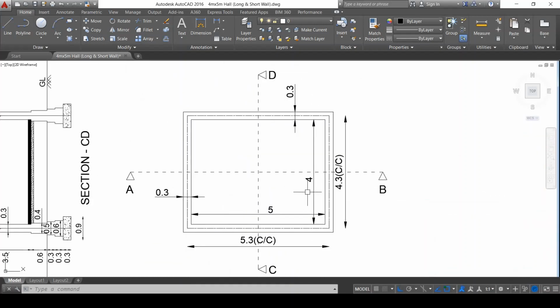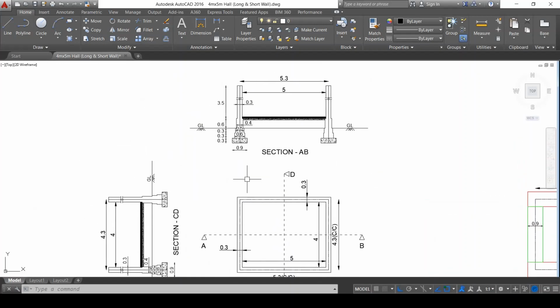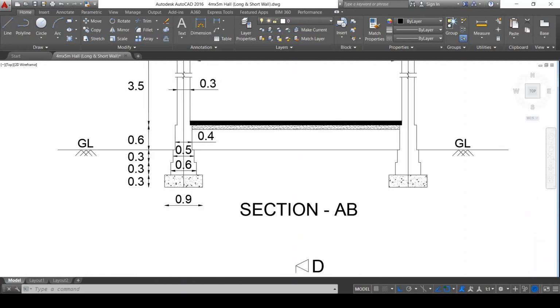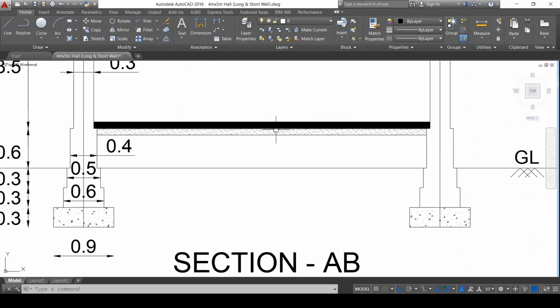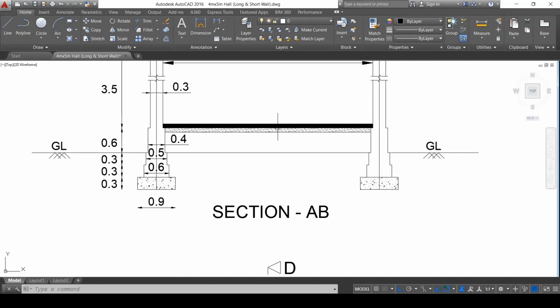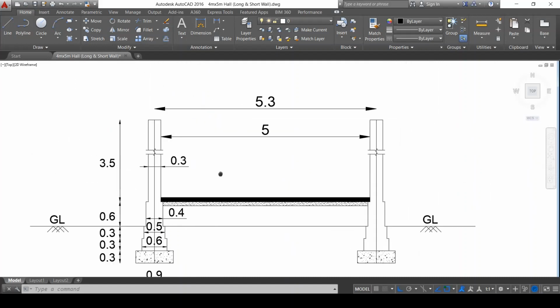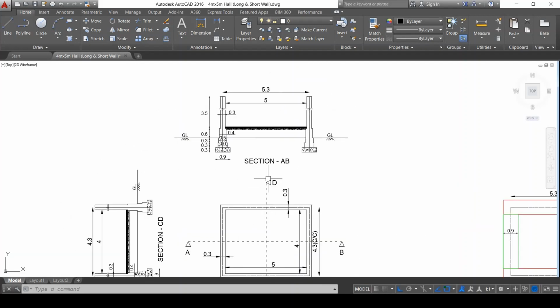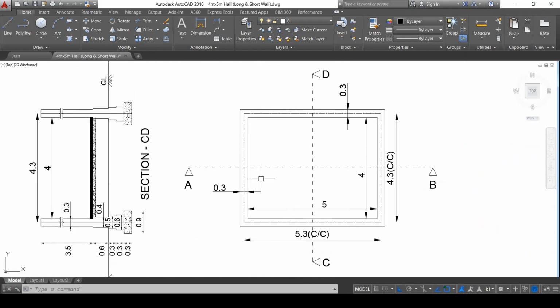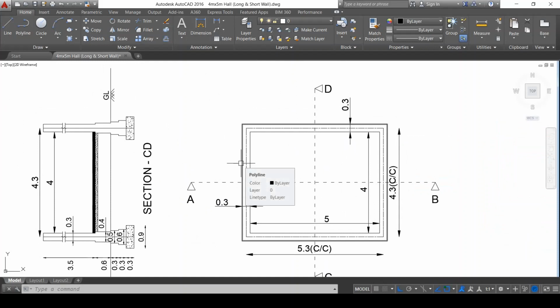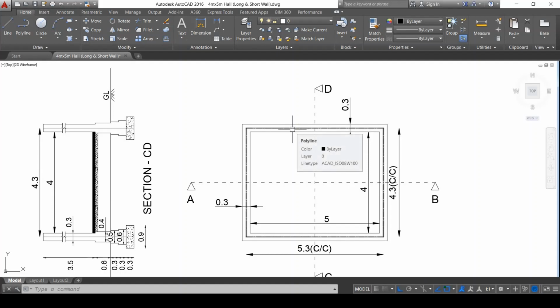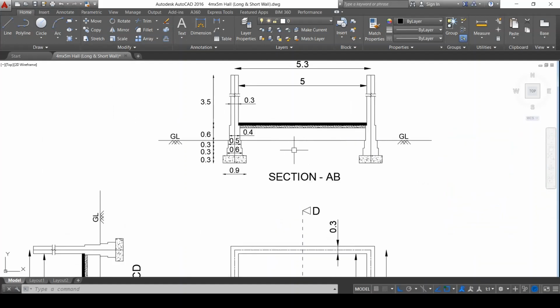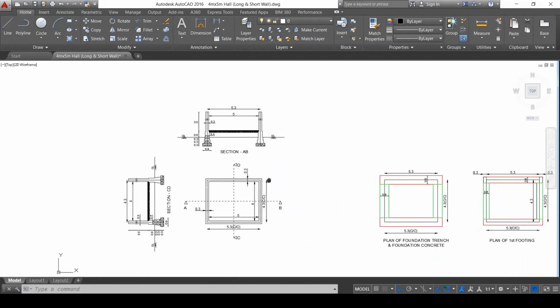It's a simple problem. We have missed out so many things because not much data is mentioned here. We can look at here, there might be, we can go with DPC, we can go with flooring, there will be a roof slab, there will be lintel, windows, door openings, everything has to be considered. Since this is the initial stage of understanding the concepts of long wall short wall method, we have considered only 4 items or 4 quantities which has to be arrived at. So we have done the calculations of these things.